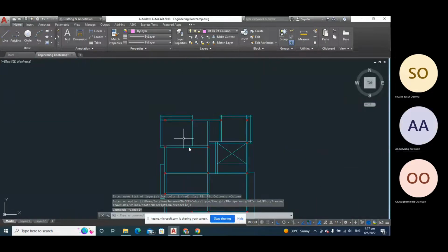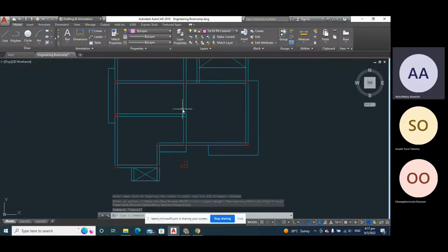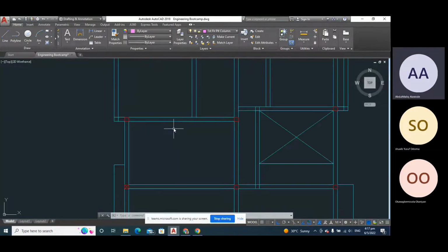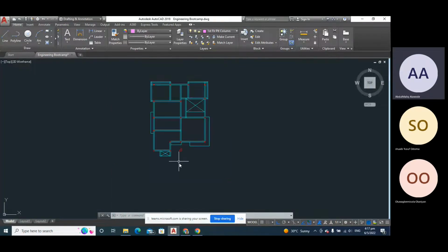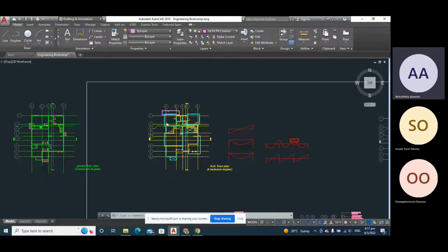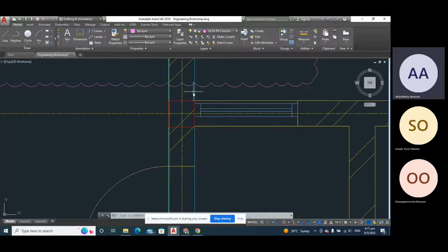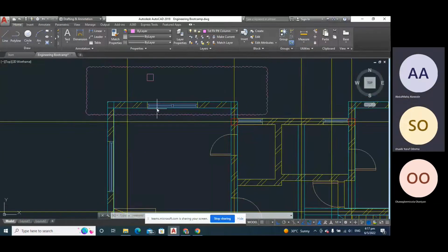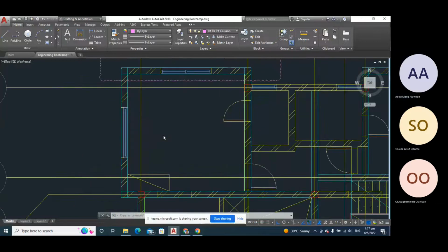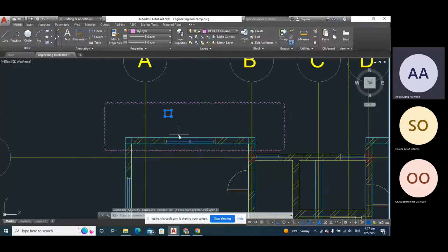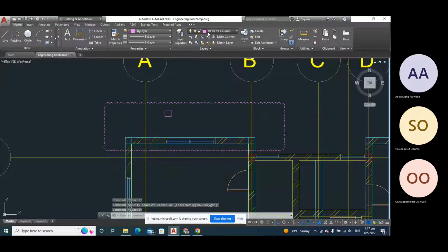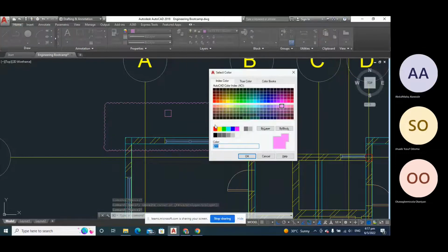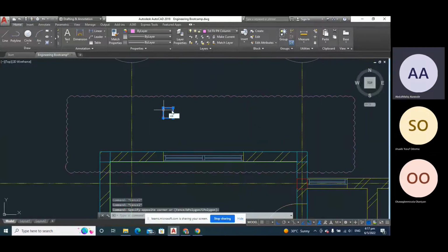Let's use red. So I'm using red for columns now. Then this sky blue kind of color is to be for our beams. So the red, this is the column coming from, those are the successful columns. The ones that will go from the ground floor up to the first floor, up to the roof. So now we are trying to fix some columns that are going to resist the load of the roof.